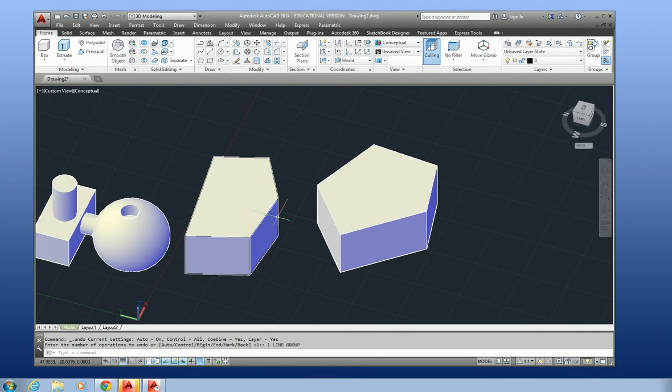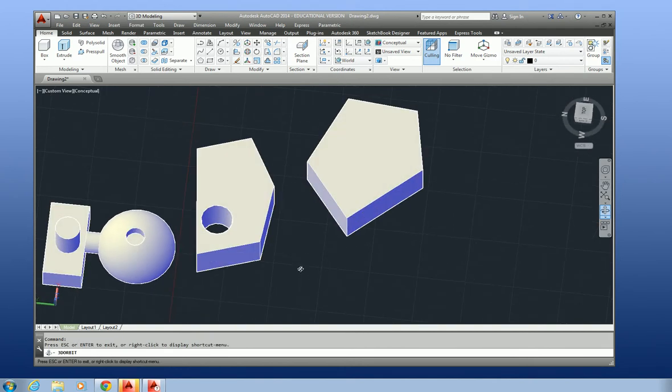Okay, so let's talk about how I want to manipulate my shape. Let's say I want to put a circle in this. Right as soon as I clicked on that surface, I was able to create my circle, but it didn't automatically extrude because I didn't pick cylinder. I just want this to create a hole, so I'm going to press pull. With press pull, you don't want the line. You want to pick the interior of this circle and drag it past the other surface, left click, and there you go. Hitting escape takes it out, and now we've created a hole.